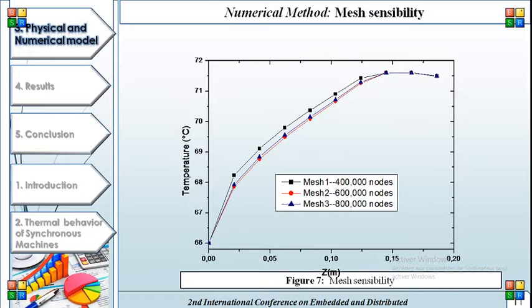So to simulate our fluid domain, meshing is performed by using ICEM CFD to create a hexahedral mesh, as shown in figure 7. The fluid domain was discretized by using a structured grid with mesh refinement. For the same Taylor number and grooves aspect ratio, we tested three meshes, three grids.